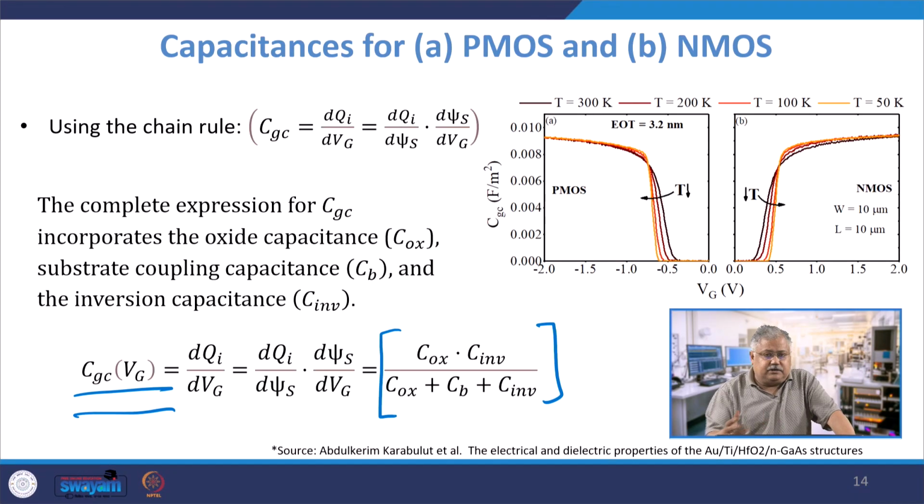In the second phase, we studied the variations, and the variation was primarily the capacitance variation with respect to temperature. Finally, we looked into PMOS and NMOS, which is what this slide is all about, with variation in temperature, and one interesting point was that there was a crossover at the threshold voltage for NMOS and PMOS, and the rate of increase is there. So, if you want to use NMOS and PMOS for all practical purposes in cryogenics, by this study you can know where you need to bias for a minimum variation with respect to temperature, and the idea is to keep it around threshold voltage.